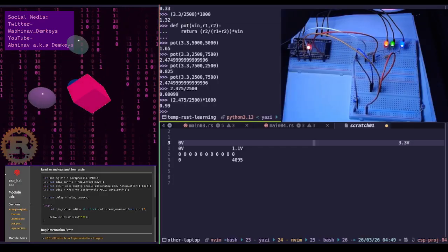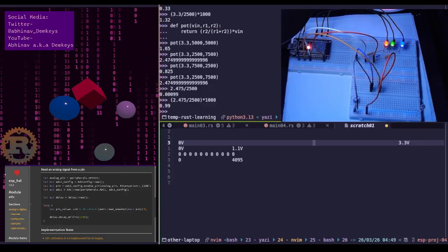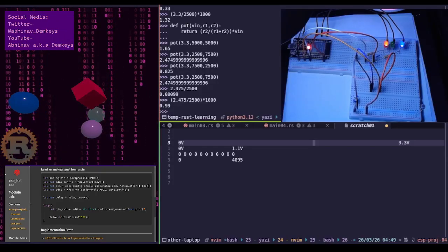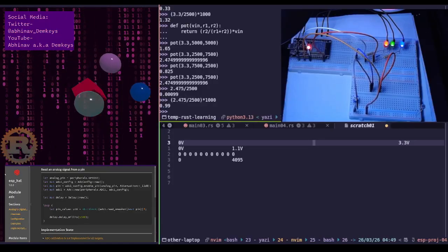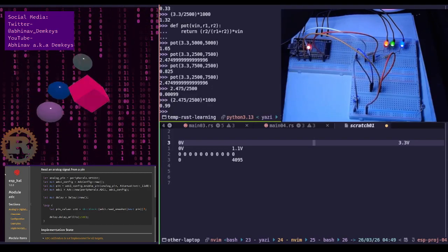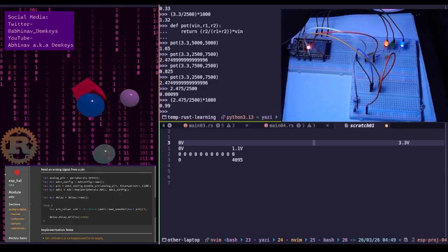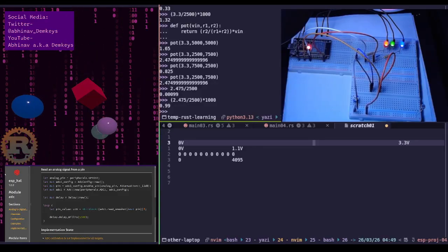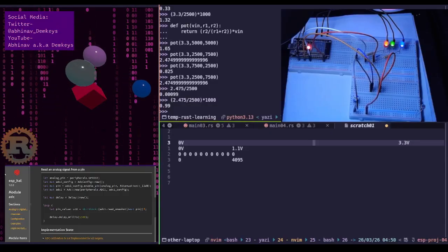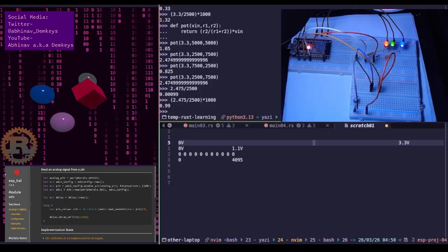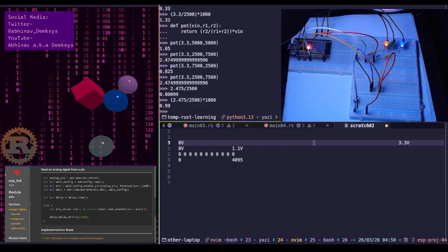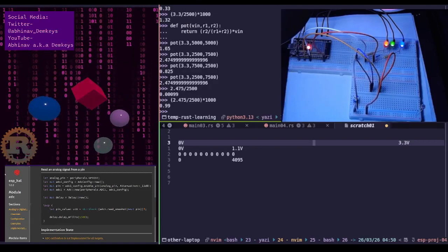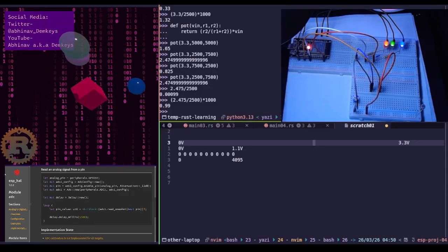When I was doing the I equals V divided by R calculation, I calculated using VCC and R. Assuming we are at 0% and we've turned the knob 25%, we would be looking at 2,500 ohms. So I did 3.3 volts divided by 2,500.